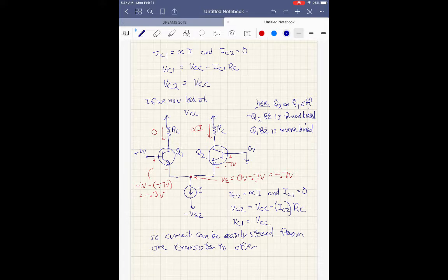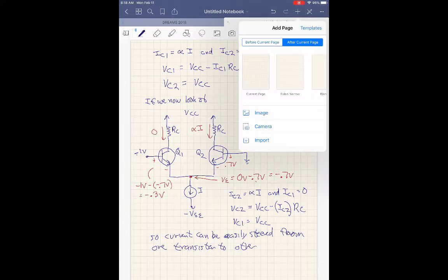This works really nice for logic circuits, for example, which are covered later in the book, I think in chapter 15. So let's take a look at one more thing, just like we did with the MOSFETs. If you remember, there's a range, what we call the common mode range. So we want to talk about what that common mode range is. There's a common mode maximum voltage and a common mode minimum voltage.